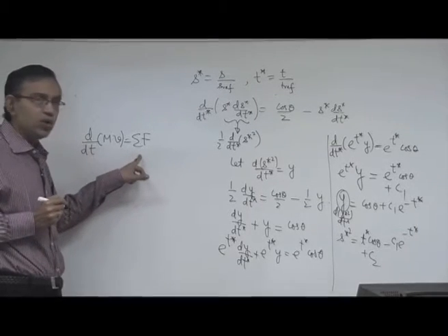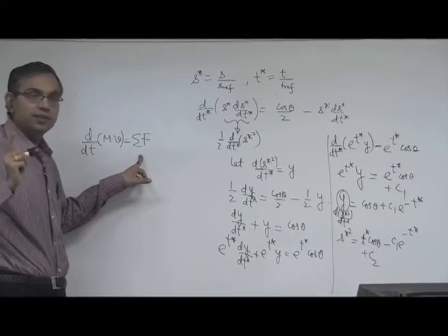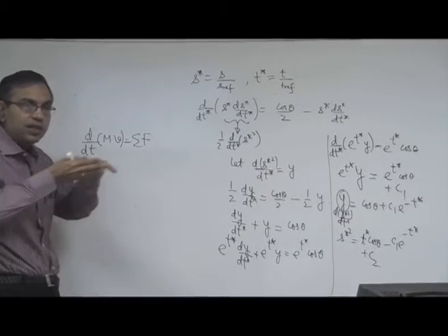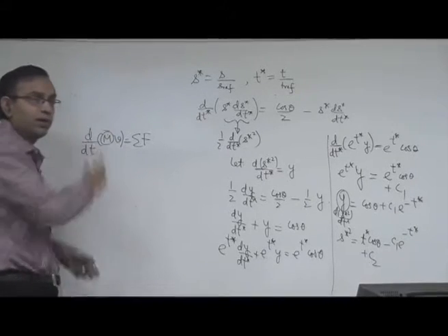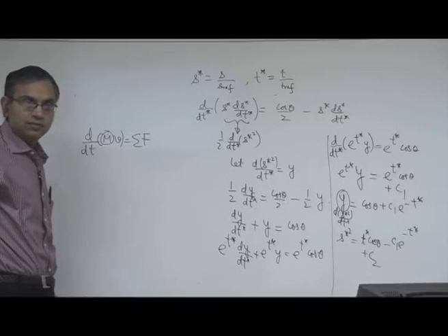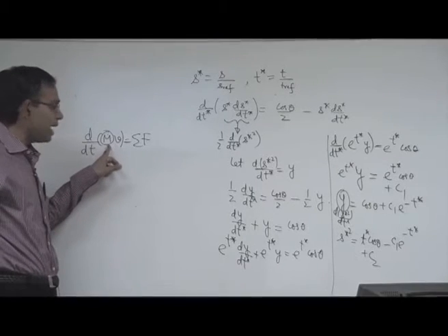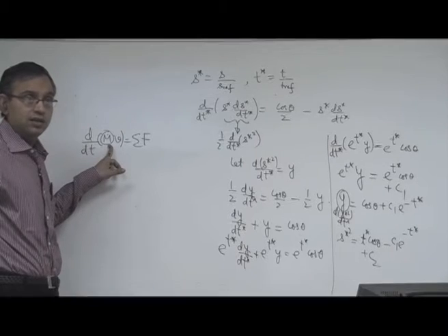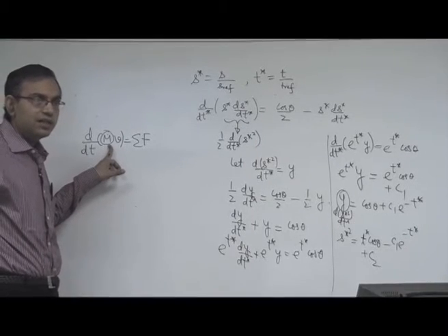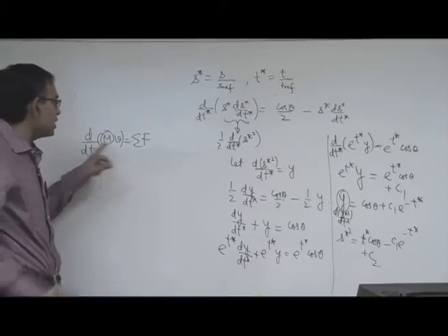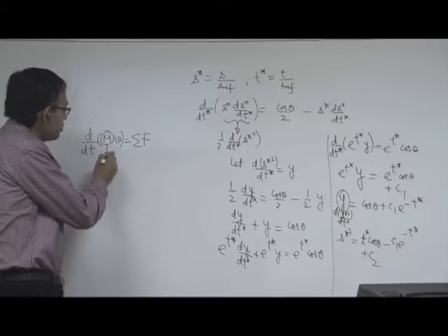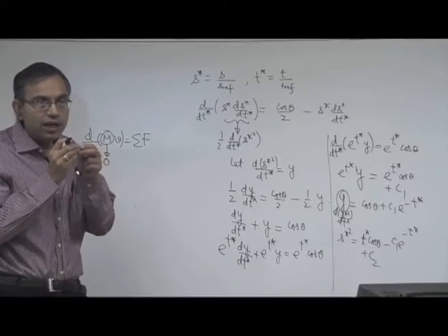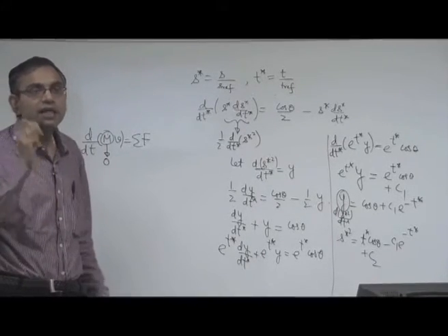This is true for a control mass system, a system of fixed mass, but the liquid that is being pushed into the capillary, this mass is a variable mass. So, somewhere that conceptual error should reflect. Where does it reflect? It reflects under that condition when m tends to 0. When is m tending to 0? The liquid is just entering the capillary, that is at t equal to 0.